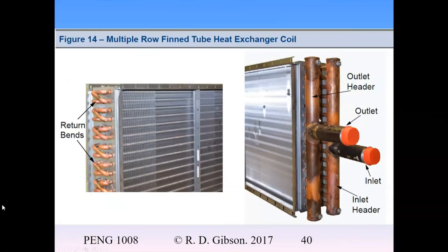Yes, so generally you're going to need to push air through this. Either, if it's in a car, the car is driving and there's air that can flow through, or it has an auxiliary fan to push air through. But we can't rely on natural convection to allow air to move through this because it just gets clogged. But you see these types of heat exchangers in all kinds of applications. And generally in this case, moving heat from a liquid to a gas, generally air, would be the prime application of this type of heat exchanger.